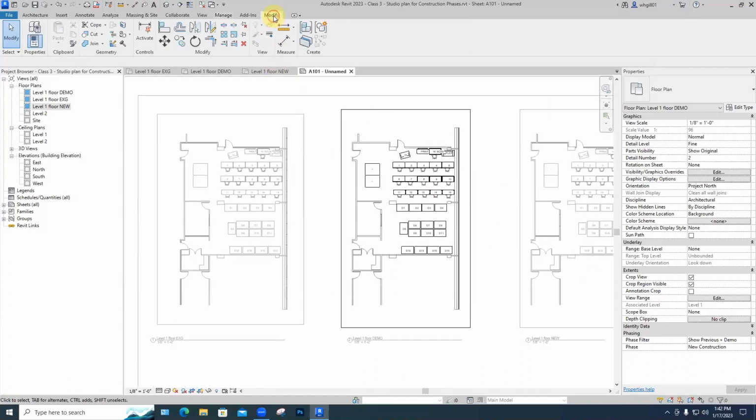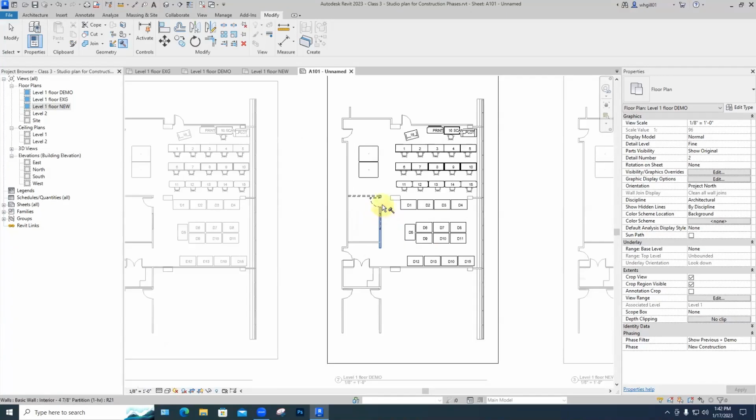And that's with a modify, two different ways. I like this one, modify demolish, use the sledgehammer on it. And this is different from erasing it. This leaves it in existing, but shows that it's demolished in the demo drawing and does away with it in the new drawing. So we can do that with any of these objects. Here's the door, we'll make go away. The window, the wall, the wall.